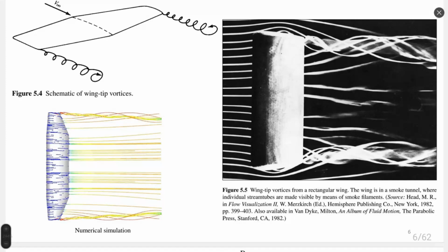The vortex by itself causes extra losses on the wing. The vortex is something that we would like to mitigate. There are several ways to reduce its strength. Most are devoted to profiling, or appropriate shaping of the wing.